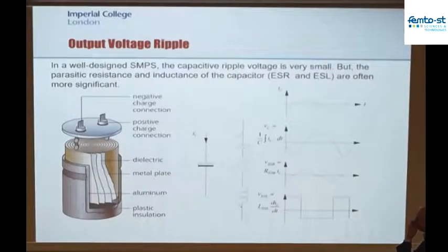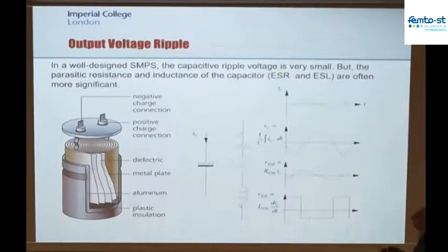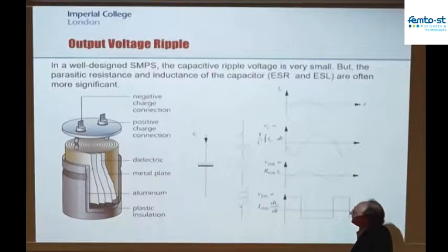So as I mentioned, the capacitor that we put in there, at least on power converters that get to be over a few watts in size, and I appreciate for energy harvesting maybe this isn't going to be a problem, but it depends how small we need to make the harvester, we're probably going to end up using some form of electrolytic capacitor somewhere. The electrolytic capacitor is a relatively poor quality capacitor because it has potentially significant capacitance, but also fairly significant series resistance and series inductance.